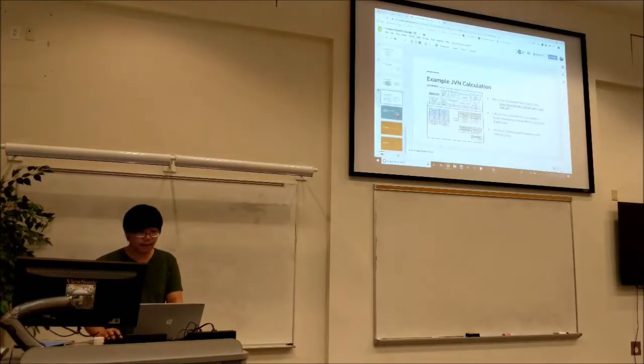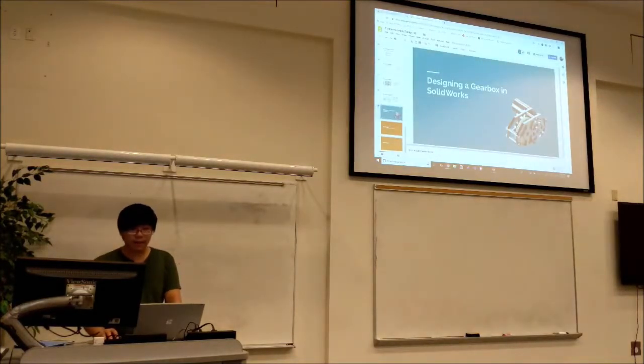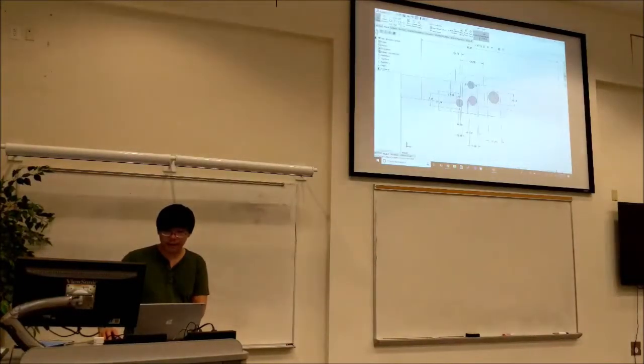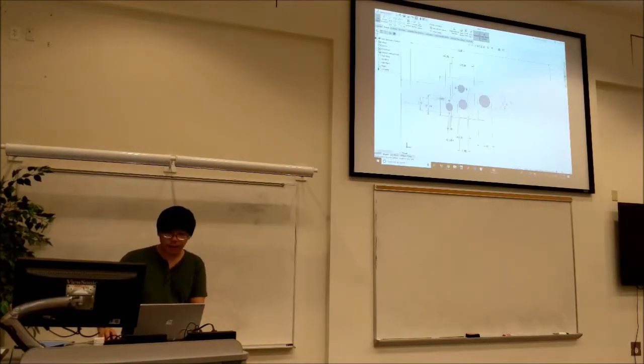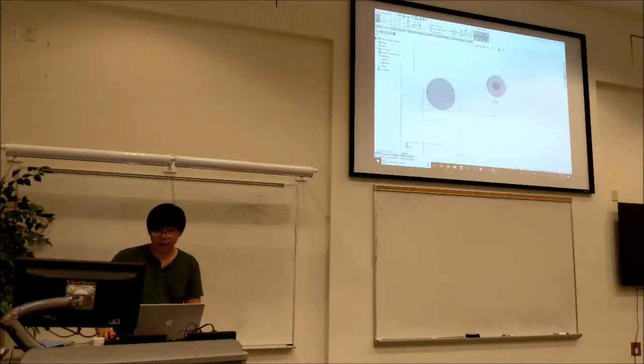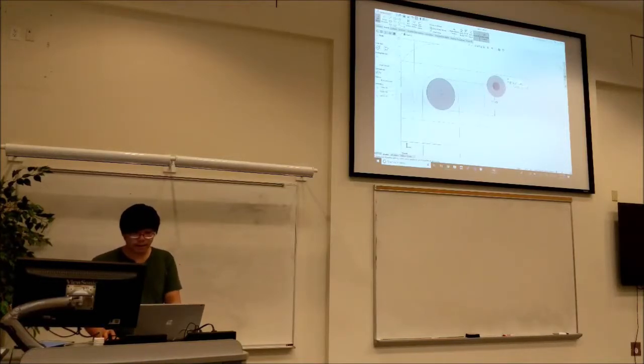If you look in the render, we have two plates that both have bearings, and they need to be connected to each other using standoffs, just to hold the plates together. And of course, those standoffs need holes to go through in the actual plate. So we're going to start modeling the standoff holes now. So we do 2 circles, and this is basically the OD and the ID of the standoff.